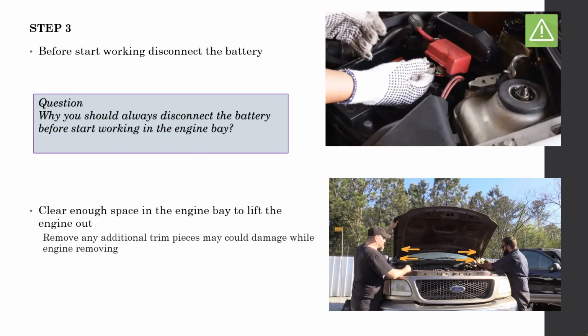Yeah. So step 3. Before starting work, before doing any work, first thing is you need to disconnect the battery, right? First thing is you need to disconnect the battery. So disconnecting the battery is one of the most important things here, because before you do any work inside the engine bay, first thing you need to do is disconnect the battery.